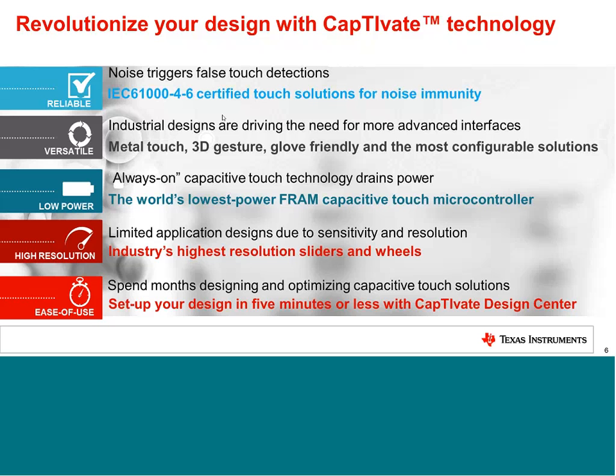High resolution. So again, when you talk about the ability to work with gloves, the ability to work through thick material and overlays with air gaps, resolution becomes very important. So we are talking of a less than 10 femtofarad resolution capacitive touch solution here.